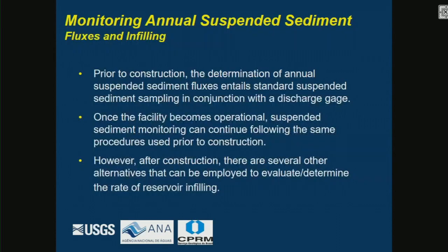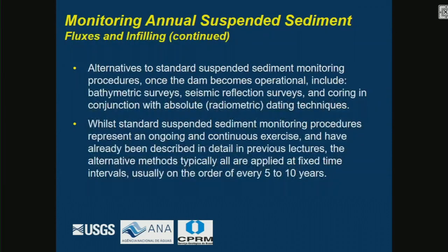Okay, so prior to that, as I said before, it'd be nice if you have sediment samples of what's going to come in. But once it's built, you have other options besides just monitoring suspended and bed load upstream of the reservoir and downstream of the reservoir. And those include simply bathymetric surveys, or seismic reflection, or coring. And so this is what I'm going to be talking about mainly.